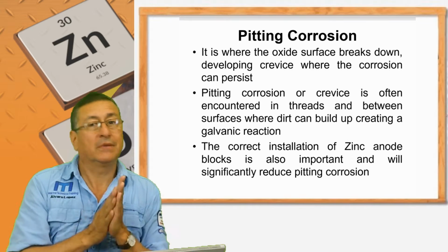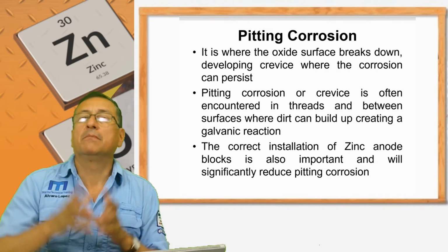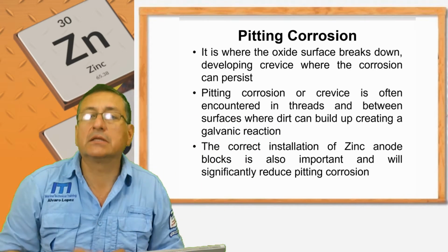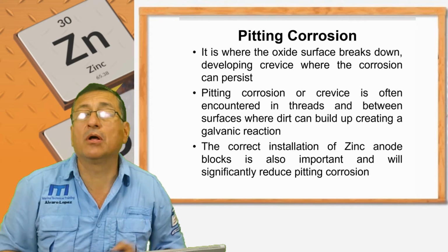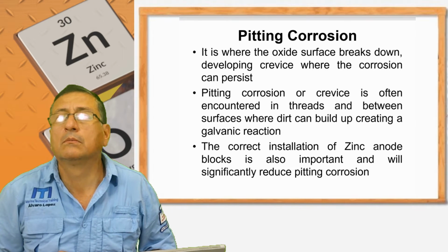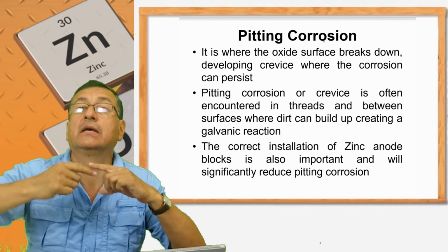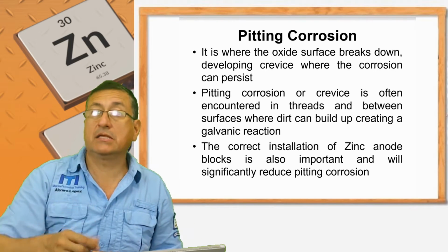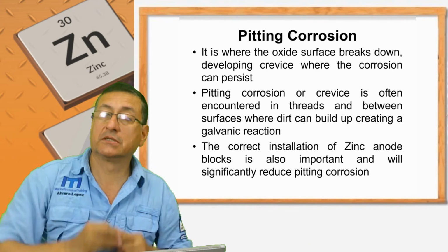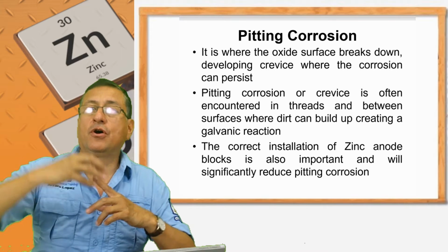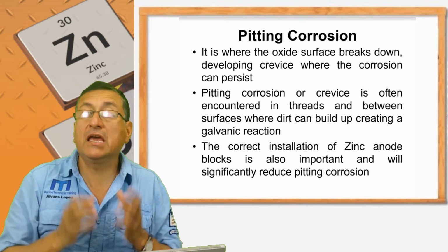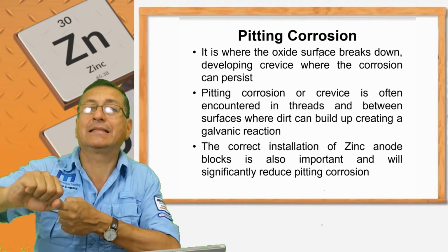For that reason, I always recommend, before you install the bolt in the block, in the head, in any part, clean the thread. With a wire wheel, clean the thread of the bolt. With air at high pressure, clean the thread on the hull. And add an appropriate seal on the threads. Loctite, 3M, they produce thread sealants. That seal avoids humidity in between the different metals and keeps the areas appropriately tight.